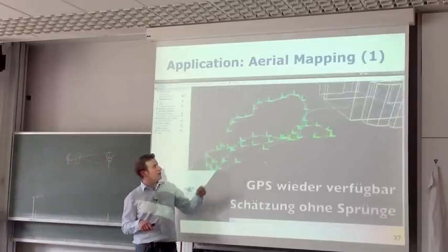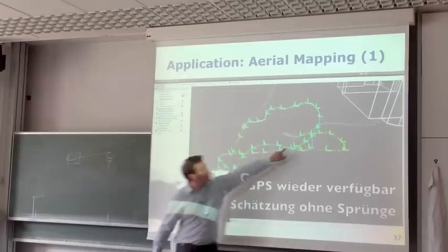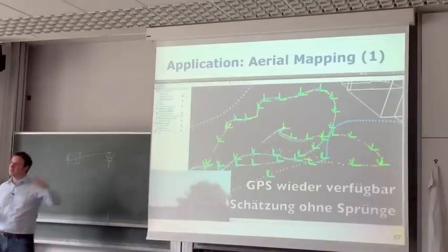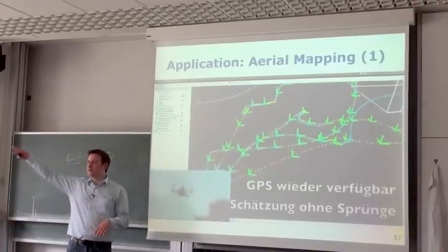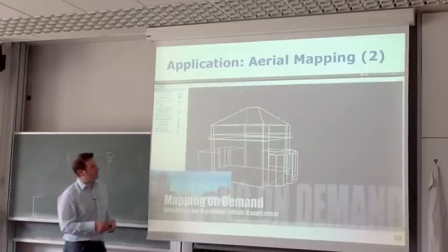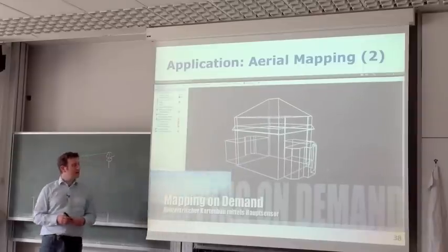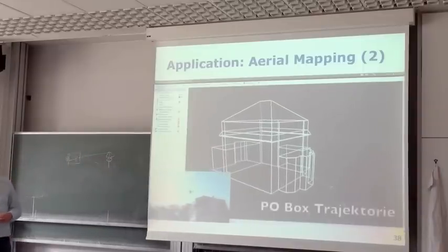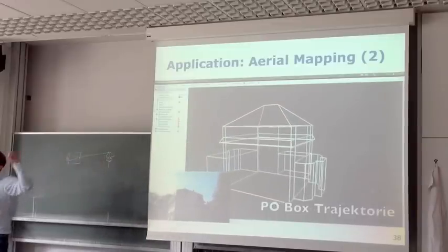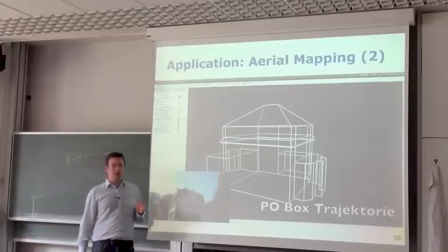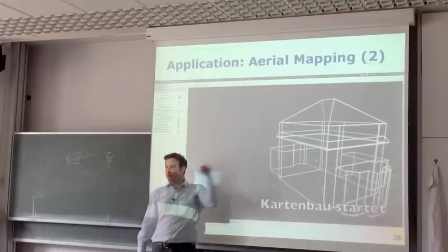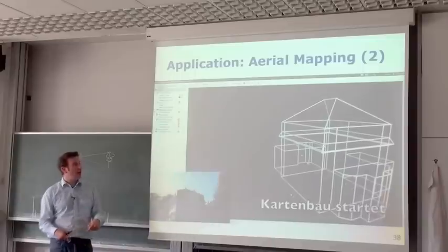Of course, the longer you continue, you can see that here, it actually recovered. What you can see here is that, of course, the cameras will drift over time. So if the GPS is off for half an hour, your camera estimate is likely to drift away. But we can estimate those things. And once we have those estimates, we can then use that to build maps of the environment. So we can fly near that building and then estimate distinct points, estimate correspondences between different images that we record, and then can estimate, given the platform was at point T1 here, at point T2 over here, observing my computer, where that is.